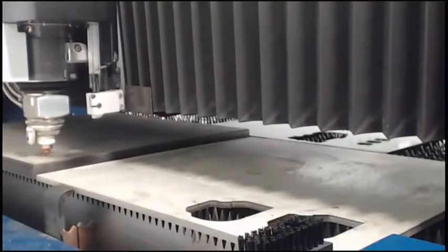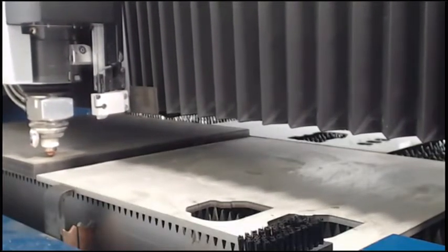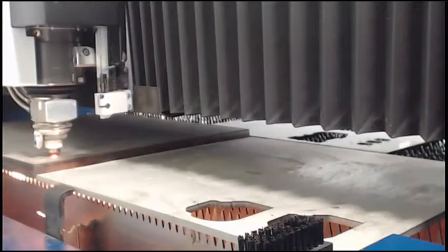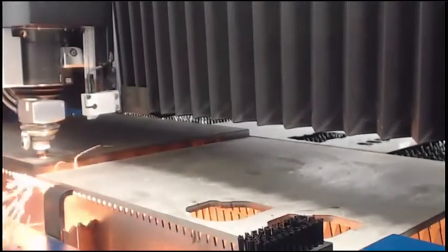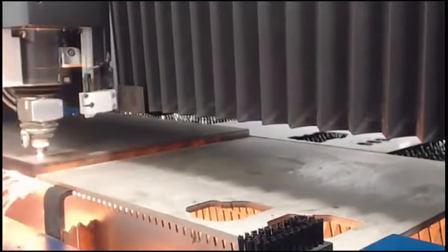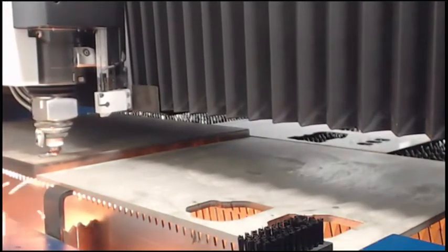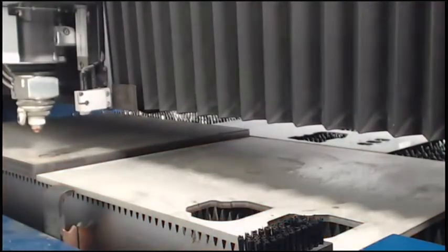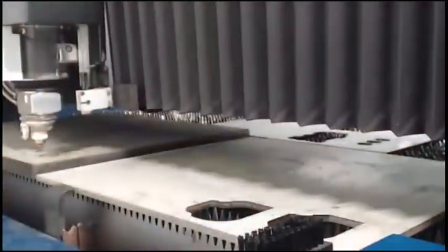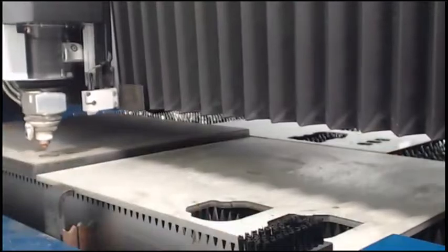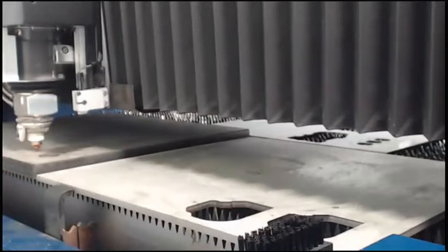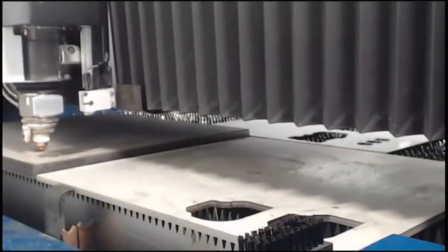Can you explain what the stages are? Because that's, I think, pretty interesting. Yeah, so what we're actually doing here is we are piercing with oxygen. It's a multi-stage pierce, pretty standard to our thicker stainless steel cutting. It allows for a really stable pierce that's also really quick and clean, doesn't leave a lot of spatter on the surface. That's really a big concern. In the past, there were stainless steel pierces where it kind of left a little mountain on the top of the sheet or a big spatter. This oxygen style pierce really goes away from that, which is really nice. You can do smaller features with this style pierce, and it's also really fast, which is cool. A lot faster than a nitrogen pierce would be.